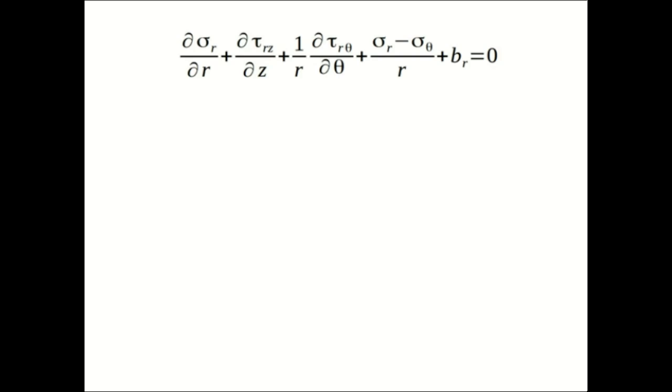The next set of governing equations are equilibrium equations. So we will find out the equilibrium equations for axisymmetric problems. Okay, we will start from the general equilibrium equations for polar coordinates in r, theta and z directions. We will start with the r direction. In the r direction, the equation will be, these are the general three-dimensional equations of equilibrium in cylindrical coordinates. So here this term will be 0, since any stress component will be independent of theta, so this term will be 0.